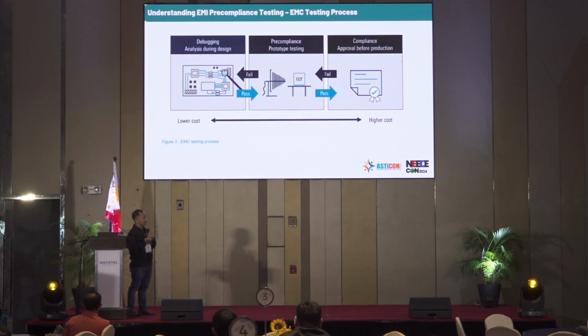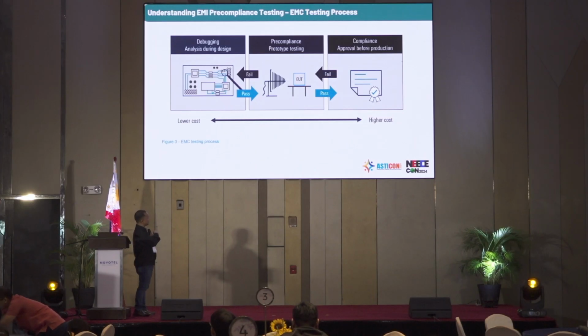Before you send your product, you need to do pre-compliance tests because this compliance test is very expensive. If you fail, you need to restart again. So you need to do pre-compliance testing first and pass that, so that you have a level of confidence that you will really pass the compliance testing.